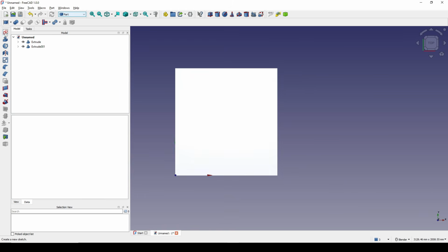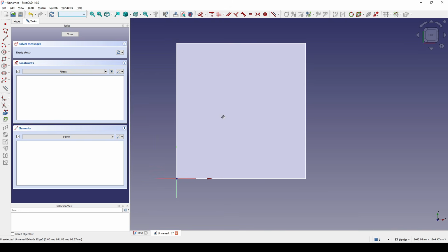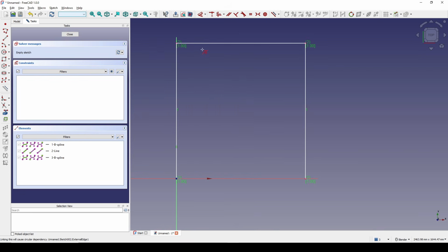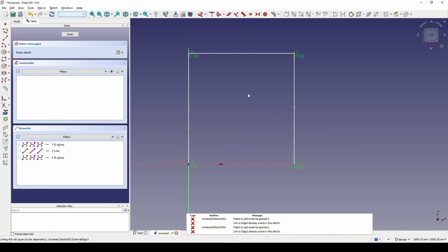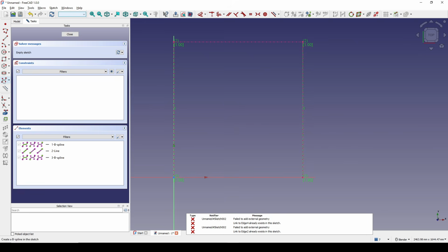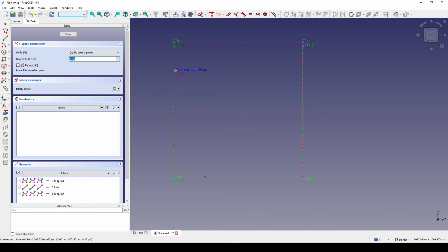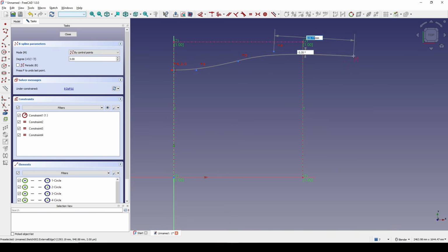I will create another sketch on the top view, and I will reference this line, and then this line. Let me view the wireframe. This one, and then I view the section. I create a line, and we start from this line somewhere in here. Put the next point horizontal, the next point up here, and the next point up here.